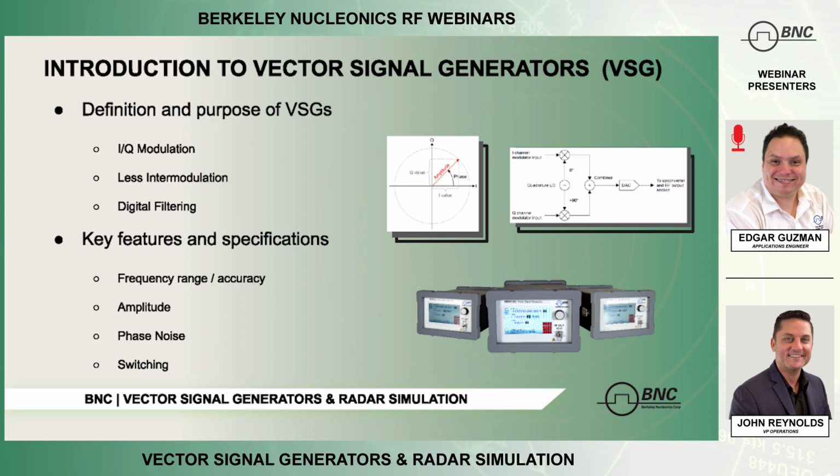Hi, thanks, John. So as John said, I'm Edgar Guzman, one of the engineers here at Berkeley Nucleonics, and I look forward to going over a little bit of what the vector signal generator can do, especially in terms of radar simulation. So a vector signal generator, as you can see from the images here, is essentially an RF signal generator that creates vectors in the IQ field, and you can see the IQ graph here. So you have vectors, obviously. You have a magnitude and phase, which is identified there.